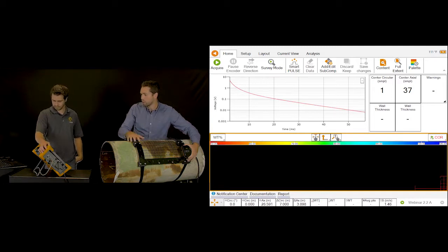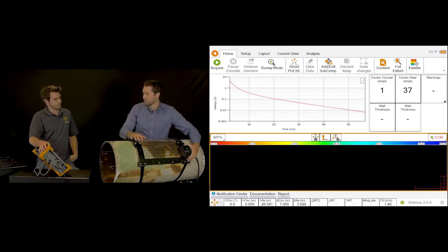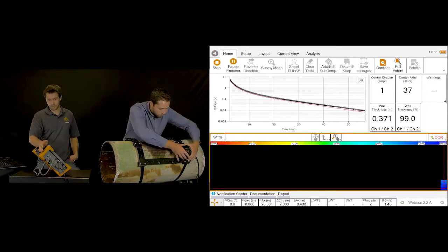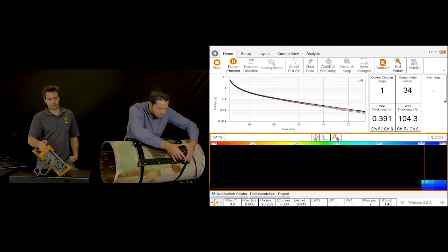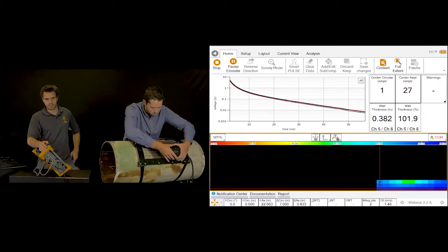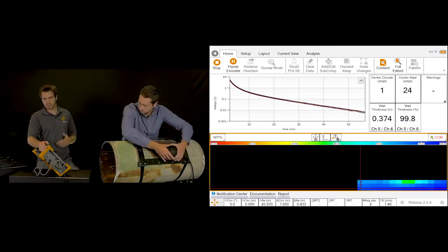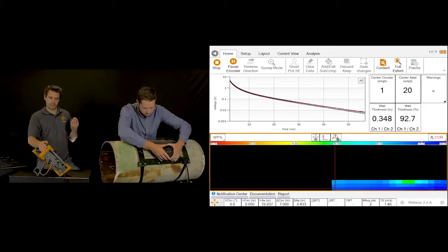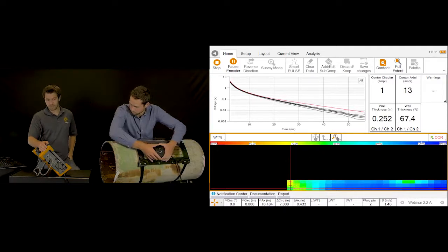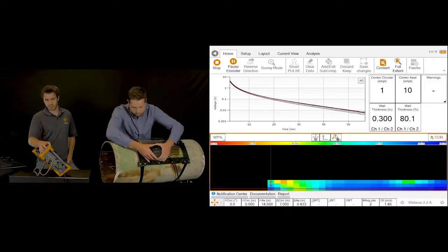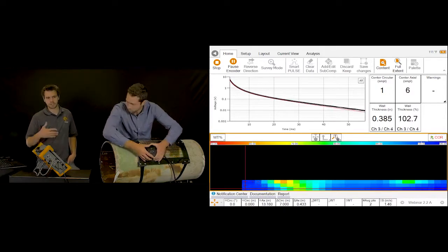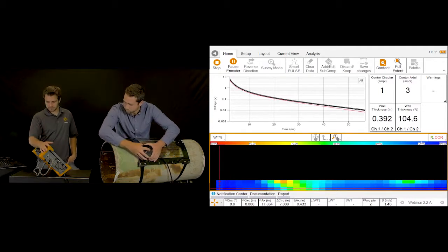First thing, could you talk about the new A-scan display? Yes, so this probe is an array of dual sensors. We have 3 elements. Each element is going to acquire 2 A-scans at once. With those dual sensors, it allows us to do a spatial triangulation, and we can really get an effective footprint which is smaller. So we can detect and size smaller flaws in the part. This is why you see 6 A-scans coming into the A-scan view at once. So every single time we are pulsing with these 3 elements, we're also acquiring data over 6 channels.